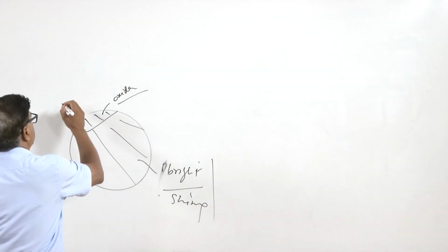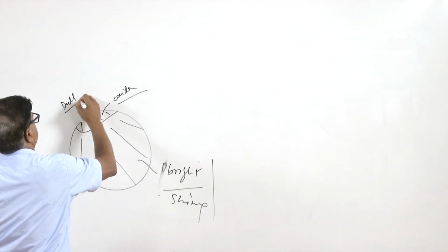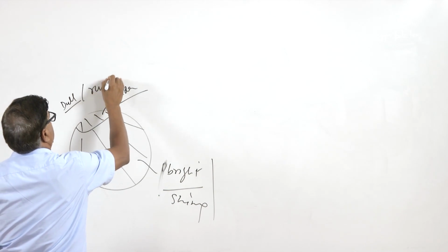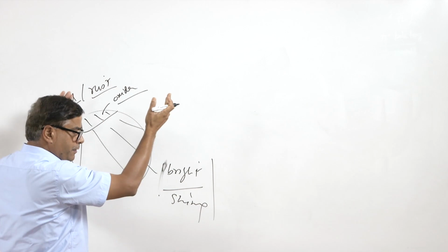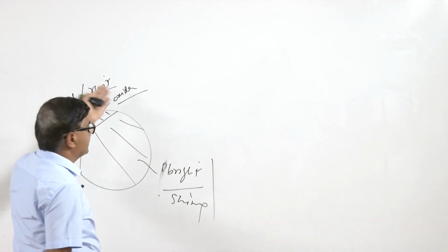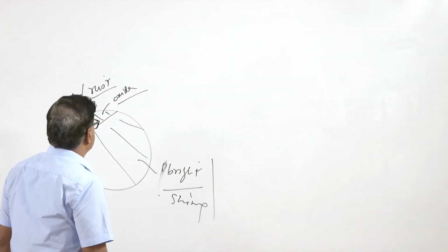While if in a particular region we can see that it is dull and there is a presence of oxide or rust, as per the metal, it will indicate it has been there for a certain period of time, because of which rusting or oxidation has taken place.